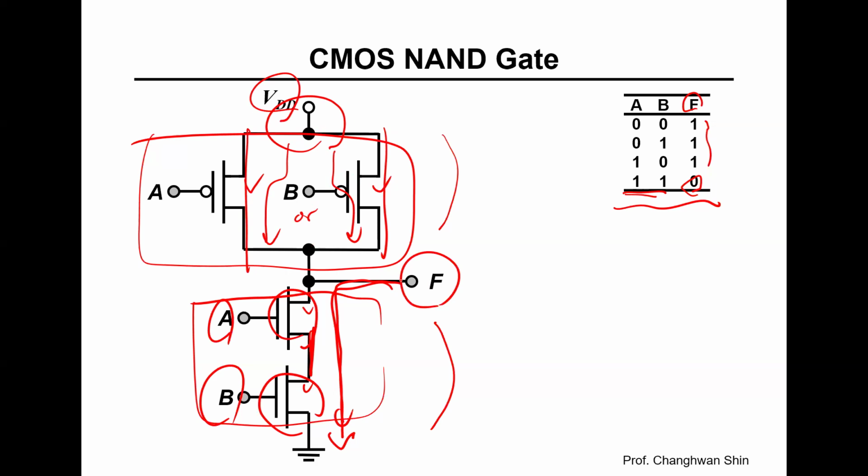So when either input A or B is low, at least one p-channel MOSFET turns on, pulling the output high. So this arrangement is analogous to home lighting controlled by multiple switches. In a staircase with the switches at the top and bottom, you need both switches in the correct position to turn off the light, NAND function, right? But either switch can turn it on.